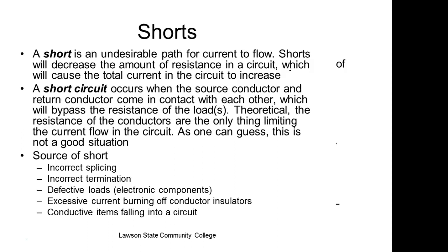If we lose our insulator, this happens every once in a while in a car, because cars have got so much vibration to them. They don't tie those wiring harnesses down good enough, and they get up against something. Over time, what's it going to do? It's going to wear off the insulation.